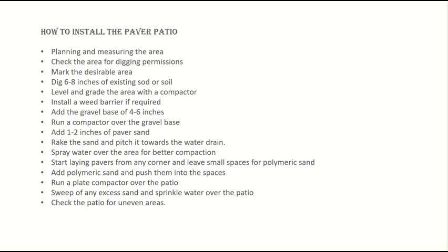Here's the thing. If you use the paver panels instead of a gravel base, we need to use a rubber compactor over the patio. Or if we don't have that, we shouldn't be too rigorous with the compacting. The reason is that the panels can get damaged. So we should only use rigorous compactors if we have a gravel base. That's the important thing to know here.